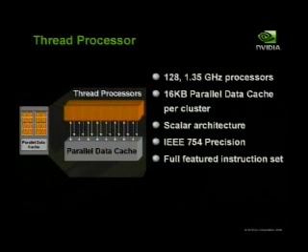Precision is a question we get a lot. Basically, it's IEEE single precision floating point that you get on a CPU, with some exceptions. We don't have denorms, so we will round to 0. But we support all the different rounding modes, and the default rounding mode is round to nearest even, like you would expect on a CPU. But it is single precision. And I've talked about the feature set. Effectively, it's very similar to a CPU instruction set, with the exception of branch indirect.